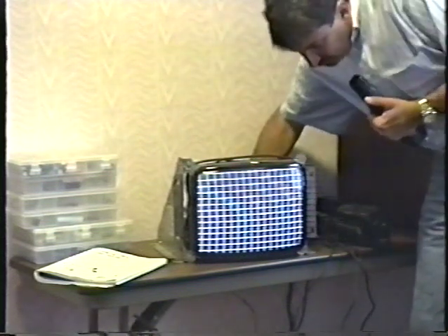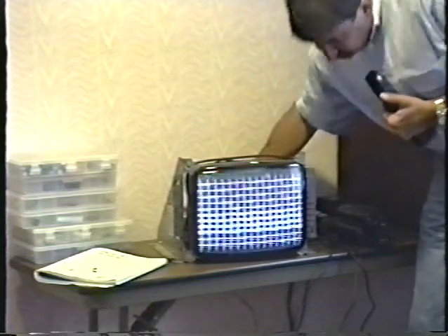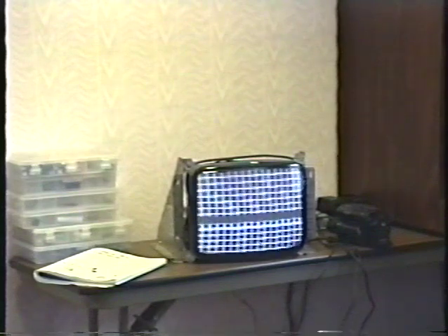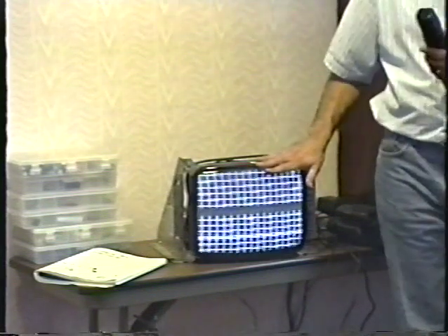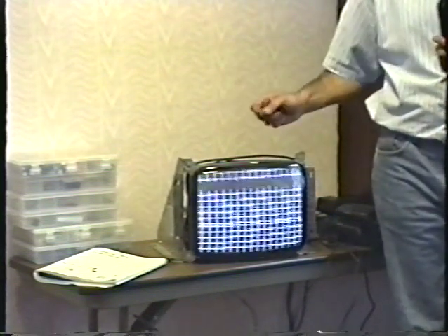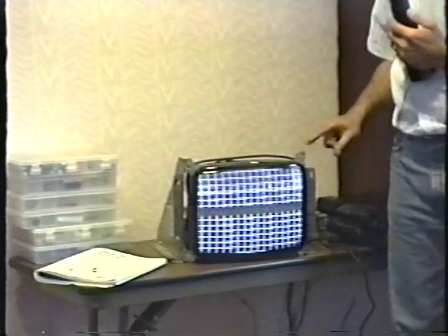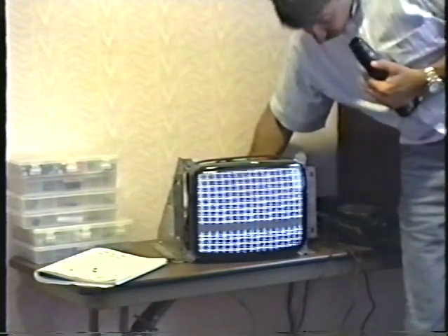If you have a problem with vertical sync, the picture rolls vertically like this. Pretty obvious that it's rolling, isn't it? The vertical sync signal keeps it from rolling vertically. Well, if you saw this on any TV, wouldn't you go right for the vertical hold control? Of course you would. If you try adjusting the vertical hold control, and you can get it to slow down, but you can never get it to actually stop, and in this case, the vertical sync is working, so it will stop.